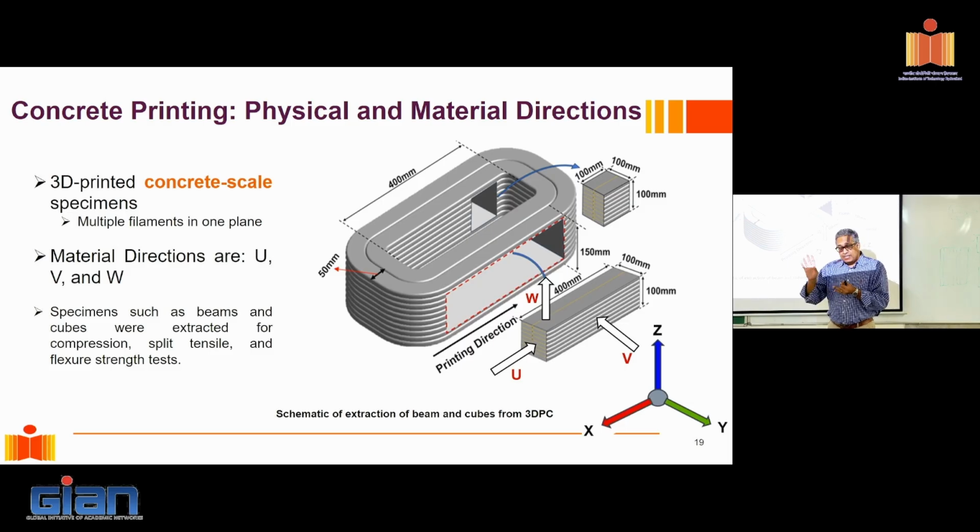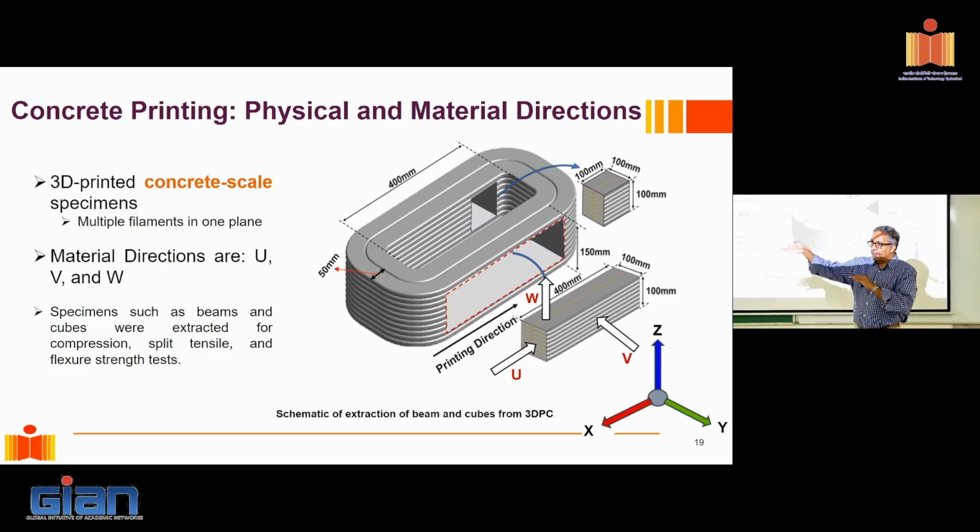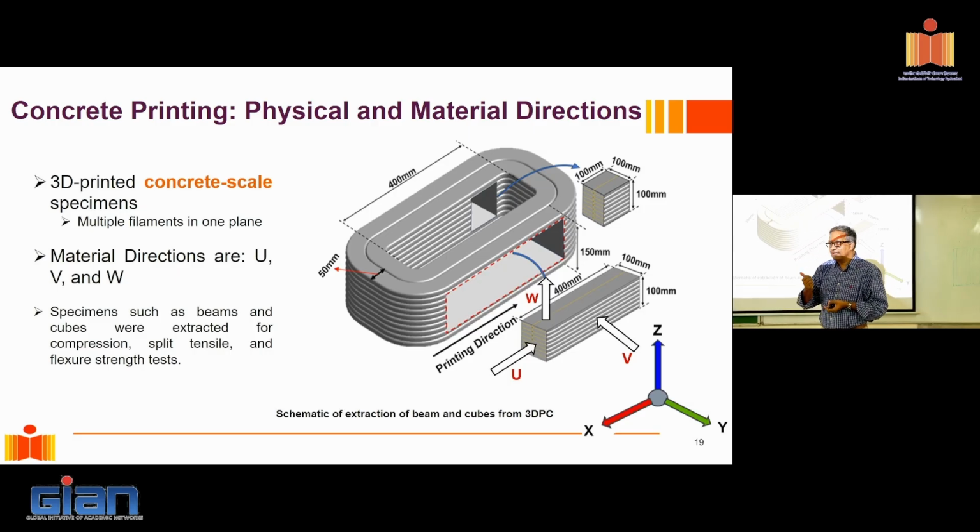Okay, I gain potentially because suppose I print a filament and I print the next filament, what happens? Now I have a fluid rich layer, fluid rich layer. So basically the chance of forming a good bond is very high, because now I have fluid rich paste on the top of the first layer, fluid rich paste at the bottom of the next layer, and so with fluid interaction, some mixing may happen and I may form a better bond. That is the idea. But what do I lose? Shape retention, because it's more fluid, it will deform, right? So when I print something, I may expect a 50 mm filament width, I may end up with 70 mm because it's much more fluid.